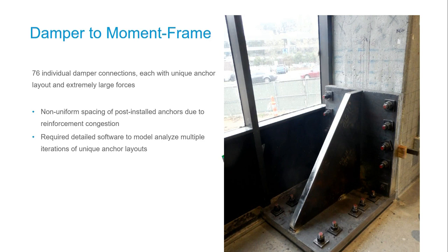Question, yes? Yeah, so at that point, we split it into 2. So we had one model for the beam configuration, one model for the column configuration, and then as we were looking at it, we fudged a little bit, because obviously there's a lot of stiffness that you get right at the end that we didn't capture. So anytime we saw big design forces up at this end, we're like, okay, they have this whole other system that's going to help support that. We don't need to worry about too much deformation there. But then again, when it's reversed and going the other way, now we have large forces there, exactly what's going to happen. Was there another question on this side?